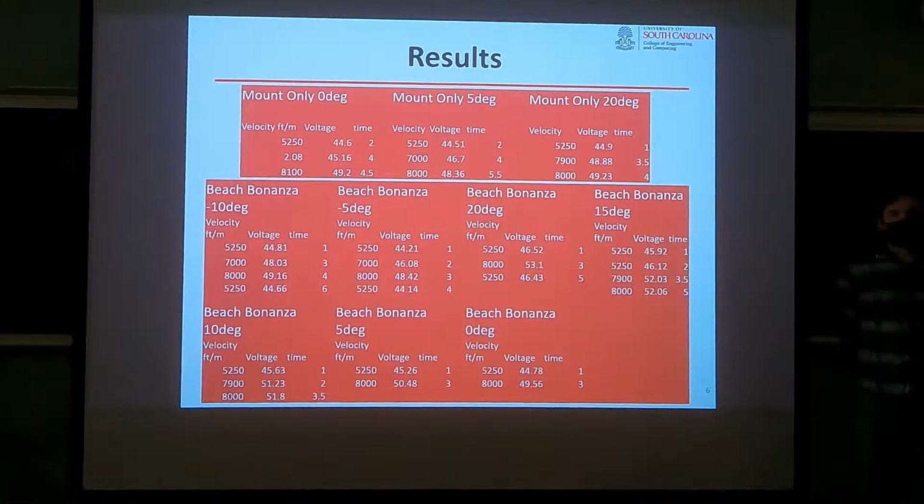Initially, we also thought that the vibrations, because that thing vibrates a lot, would impact the results pretty harshly, but it kind of didn't. It all depends on the accuracy, the build, and the filters in the load sensor, because the filters are supposedly there to cancel out any irrelevant signals like vibrations, and also the sensitivity of the, what do you call those sensors? Strain gauges. Yeah, the accuracy of the strain gauges.